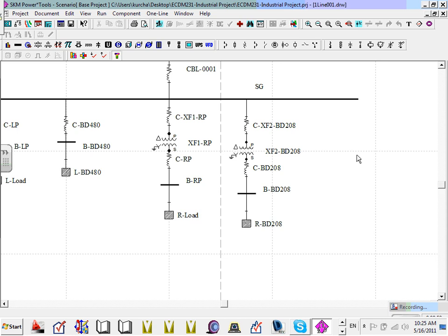Okay. I want to give you a break in a second here. I want to do mechanical panel 1. Here's a difference between mechanical panel 1 and the lighting panel. Mechanical panel 1, guys, has a lot of motors. Just because of the timing, here's how we're going to model it. First of all, it's going to look like a lighting panel. There is no transformer for mechanical panels, right?